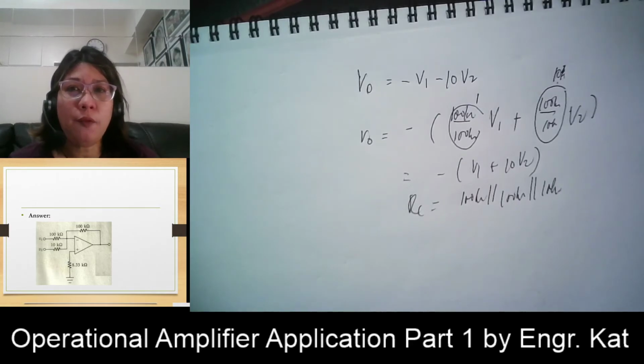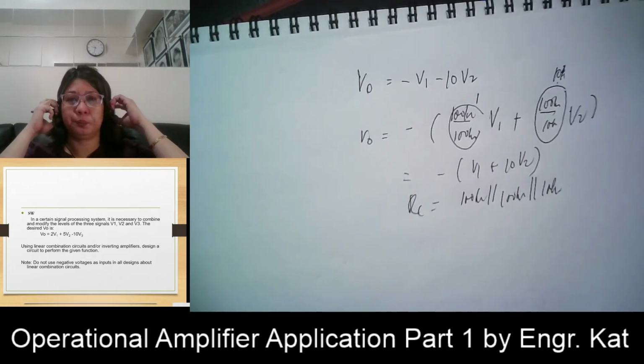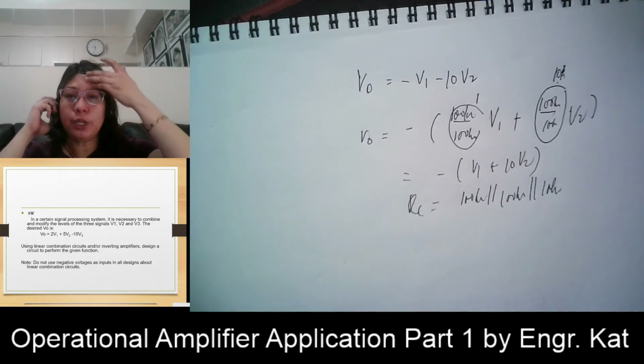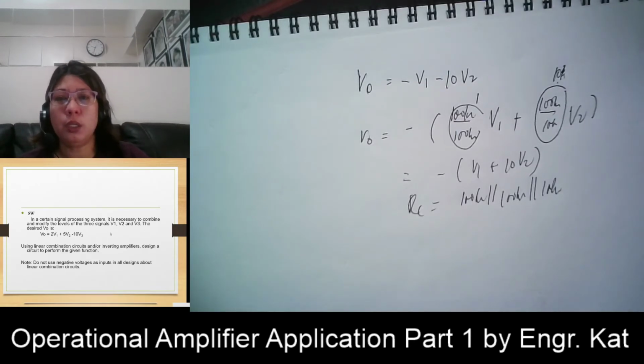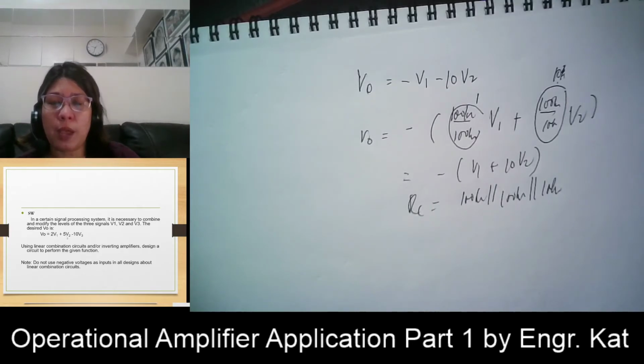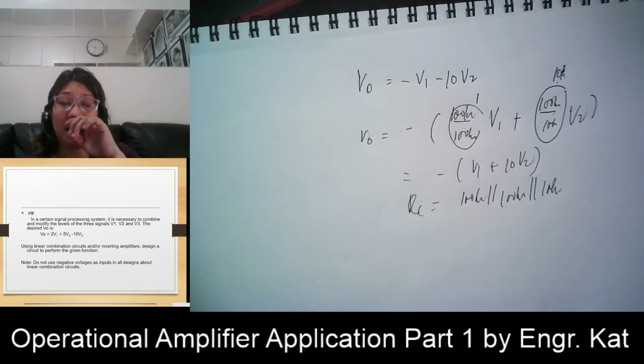Okay? So I have here a problem, and that will serve as your activity. So it says here, in a certain signal processing system, it is necessary to combine and modify the levels of three signals V1, V2, and V3. So the desired VO is 2V1 plus 5V2 minus 10V3. Okay. So what we need is a non-inverting output, since this is positive. But it says here that you can make use of linear combination circuits and or inverting amplifiers only.